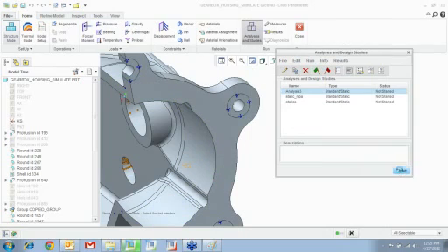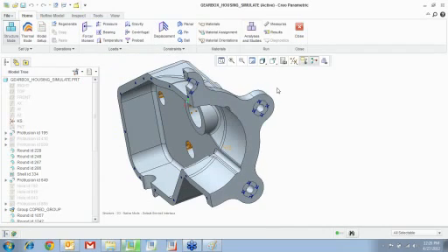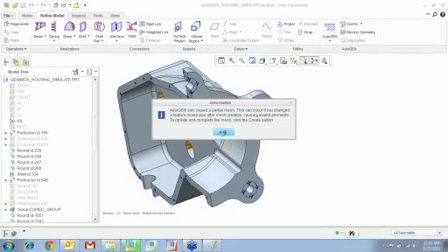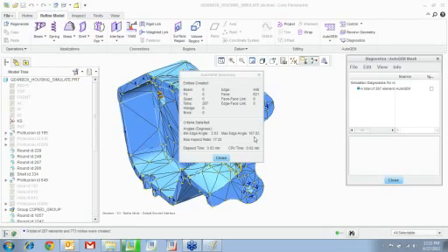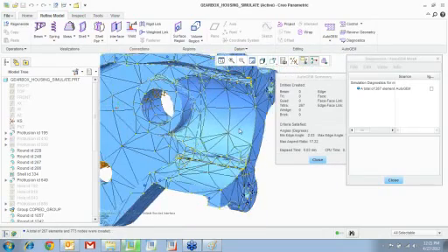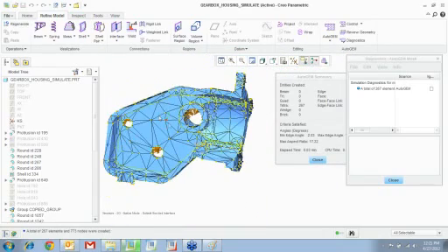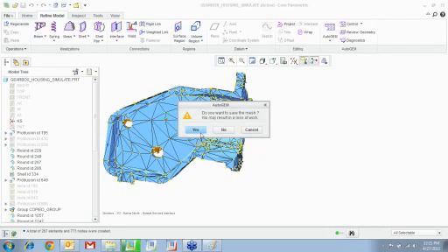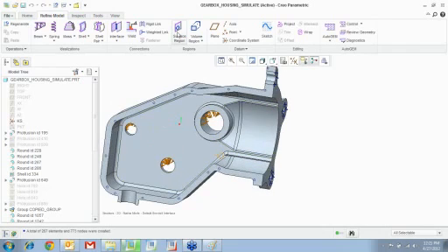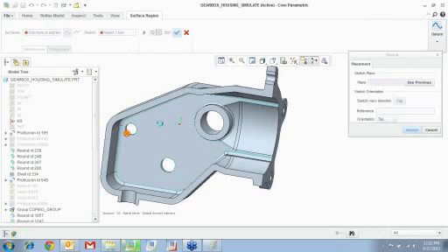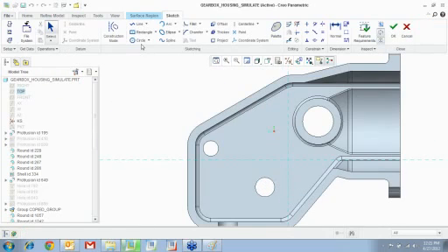Okay, so now let's go ahead and create a mesh. So here's the mesh. You can see the elements over here, for example right here, are larger, right? So what I can do right now is go create a surface region, or a volume region per se, on that surface, and let's say I want to create a box.